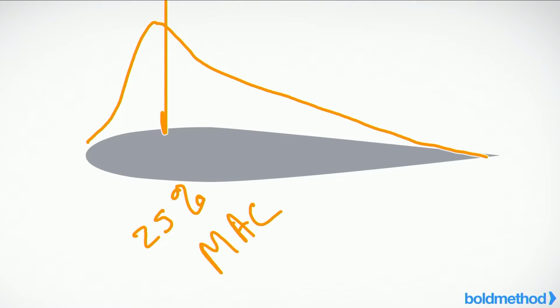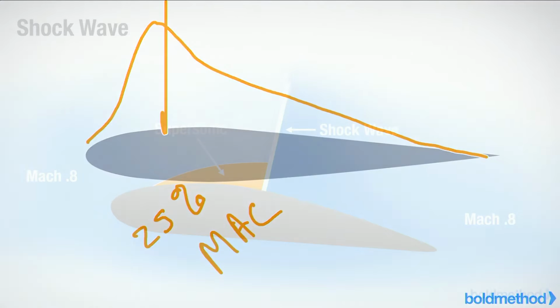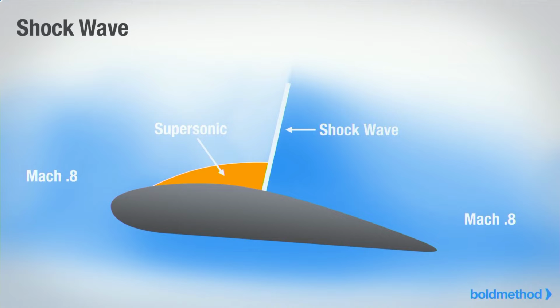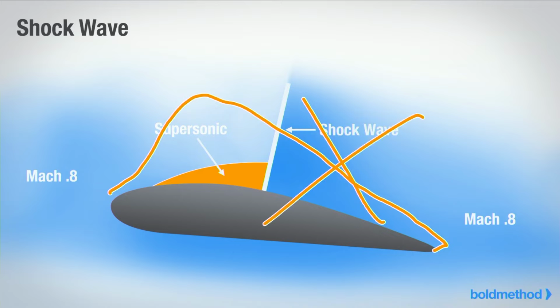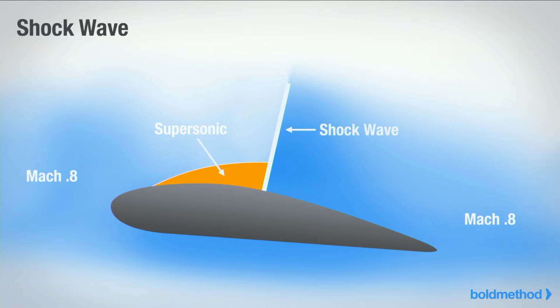The problem is when we start to add a shockwave. So let's go back to our shockwave slide. Everything gets messed up. Okay, we used to have this lifting force which looked kind of maybe like this and trailed off. Well, all that's gone now because you're not generating lift generally behind that shockwave. So now all of a sudden the airplane loses a massive amount of lift.